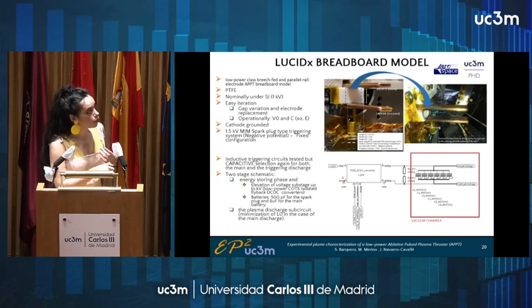Inside the storing stage, we have first a converter in order to elevate the voltage. These are converters whose specification is that they are isolated, in order to have safer electronics. With them, we charge the capacitor directly at high voltage.